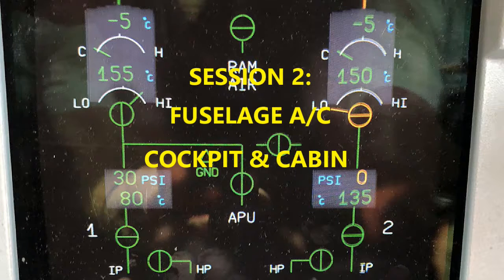So now you know there are anti-ice valves. There's also a bypass valve I mentioned earlier. Those are installed in the ducts downstream of the primary exchangers. They split that hot airflow between the air cycle machines and a bypass. Those are located in the same area I mentioned. Remember panels 191 and 192, the air conditioning packs and those two numbers.